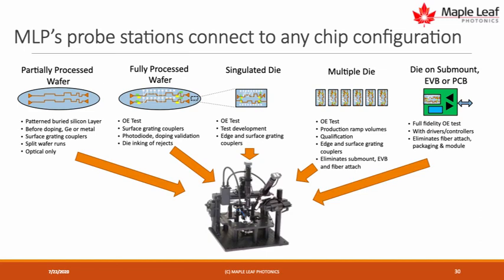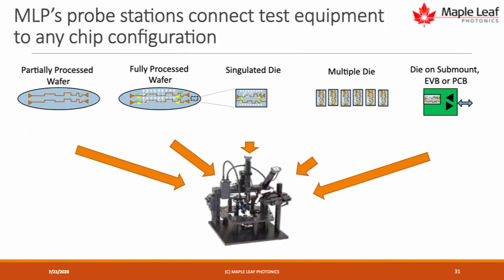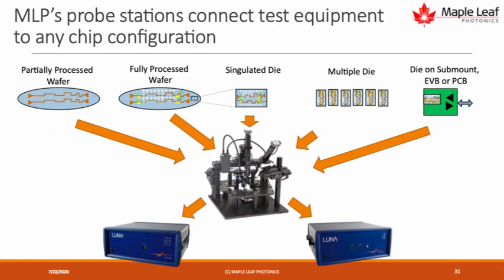If you step back and take a look at this as a whole, what you are seeing now is you can identify what each of the steps in manufacturing does to your chip. If there's a change in stress due to a die bonding process, solder, say, or glue or epoxy, you'll see it, and you can see it as your process flows. And so you can compare the performance in wafer form versus singulated die, or in a submount after the singulated die, and you can see what the effects are of those processes on your chip.